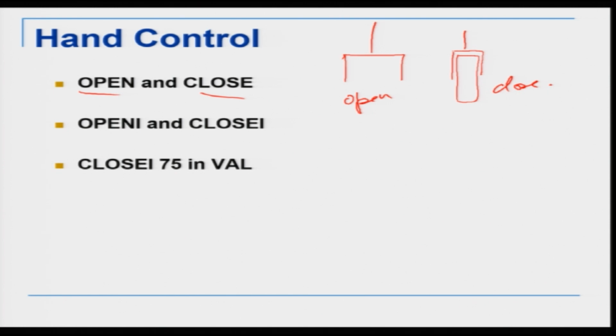Now, there is something important here which we should keep in mind, that suppose I have an object on the table like this. Okay, this is a table and I have kept an object, and this is my object on the table. I want to go and catch it. So, what we will do is, this is my gripper, this is my point P1, this is my point P2. Okay. Now, suppose I write a program like this, in which I want to pick up this object which has its CG at P2.